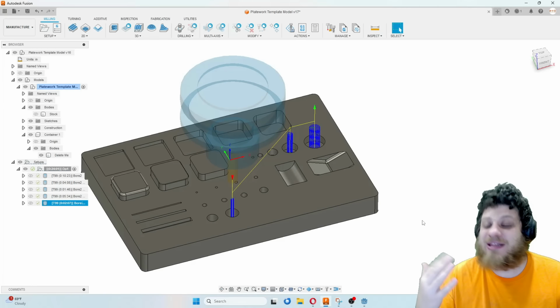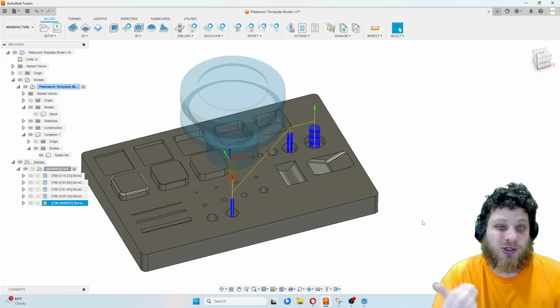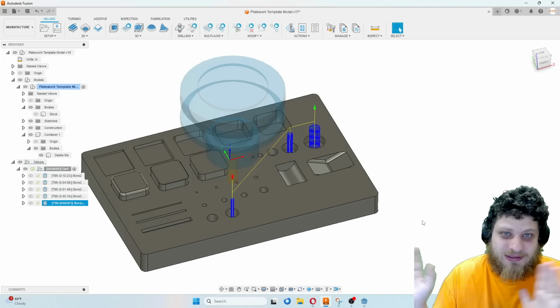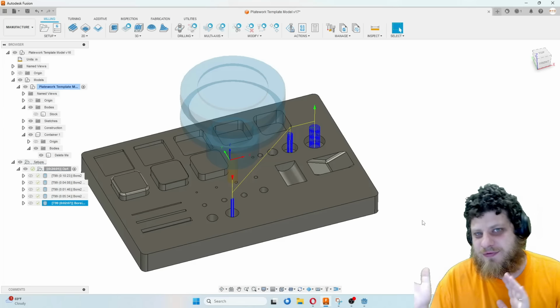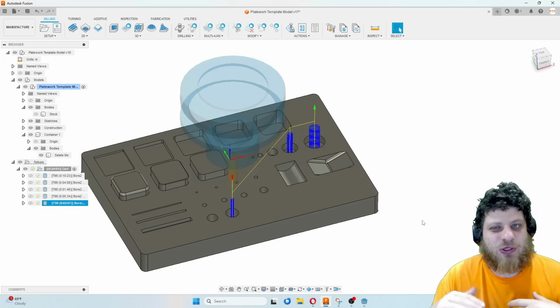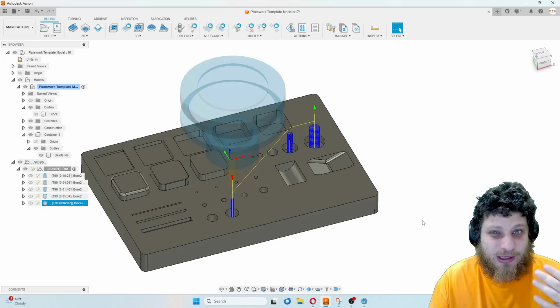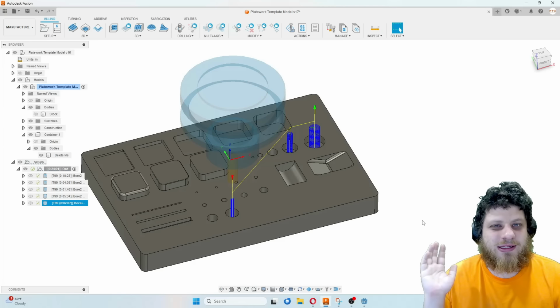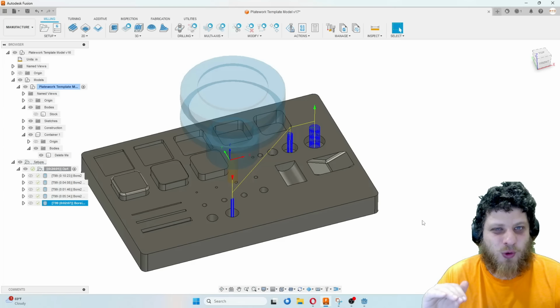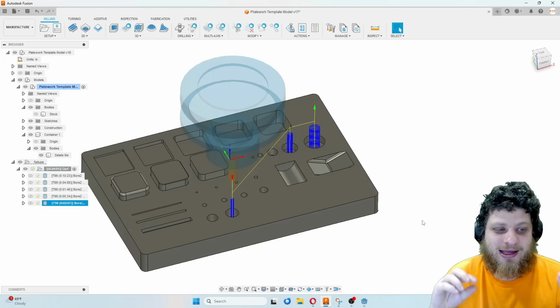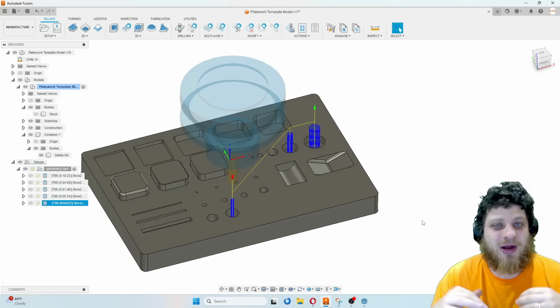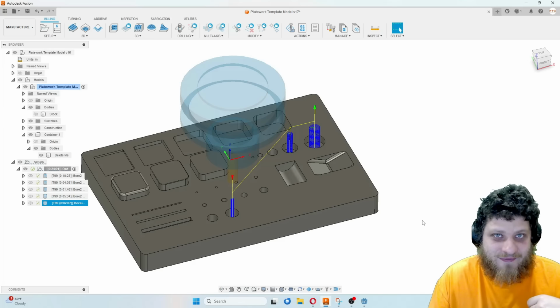1/4 inch is actually the biggest tool that I consider to be a core tool. It's like the biggest tool that I'll keep set up in the machine out there. I make really small stuff, so there's no need for me to go bigger than that. Obviously, tune this for whatever makes sense for the kind of work that you do. I would be shocked if most of you guys are boring holes with 1/32 inch end mills. That's kind of a me thing. And I would be surprised if most of you didn't have something like a 1/2 inch or a 3/8 inch end mill in here.